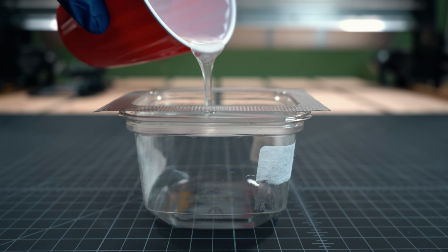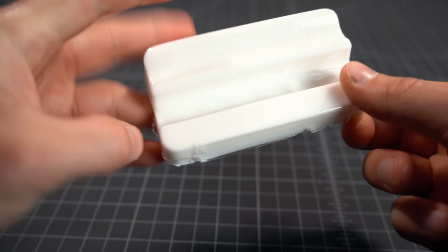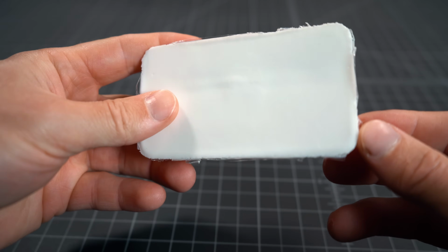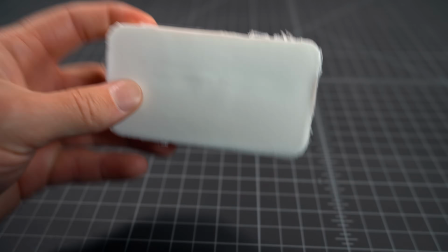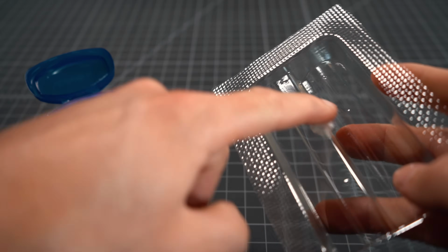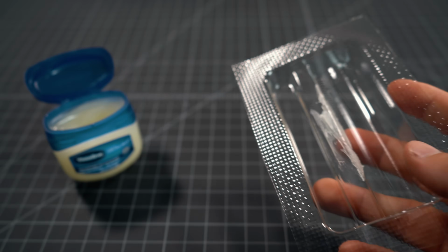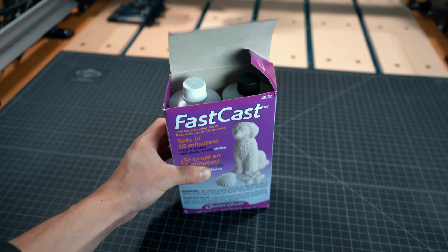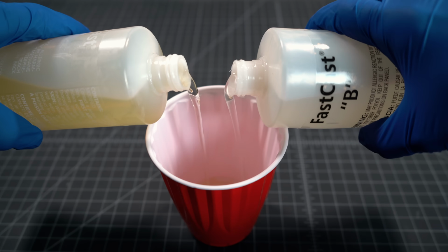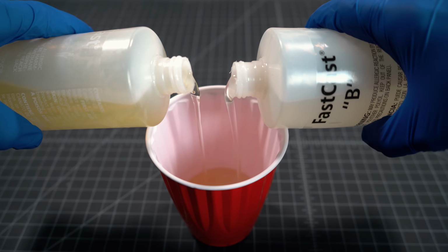The second issue I ran into came when I poured the two-part resin into the mold. Thinking that my draft angles are sufficient, I didn't consider a release agent. Thus, my first pour remains forever stuck inside the mold, and you can see that I even gave up trying to cut the mold. After some research, I discovered that a small amount of Vaseline or some cooking oil is the perfect solution. This two-part epoxy is one of the few that has little to no odor. I picked it up on Amazon for about $25 US.